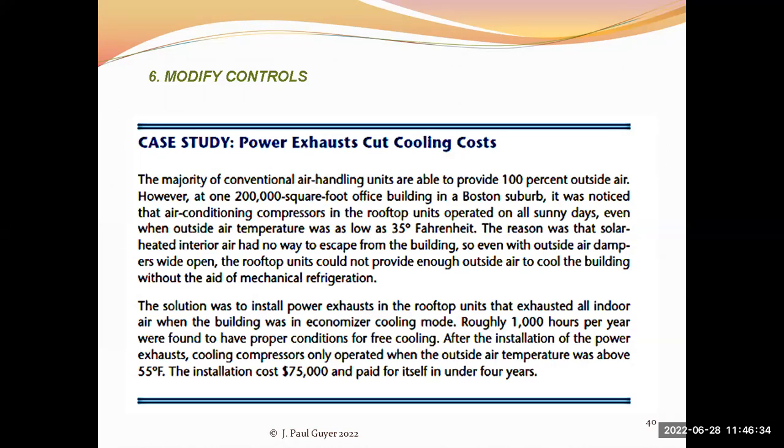Sometimes a power exhaust fan is used in conjunction with an economizer. In other words, the exhaust air, the return air that you want to exhaust to the outside of the building, it may be appropriate and feasible to install a powered fan to suck that air out of the building.